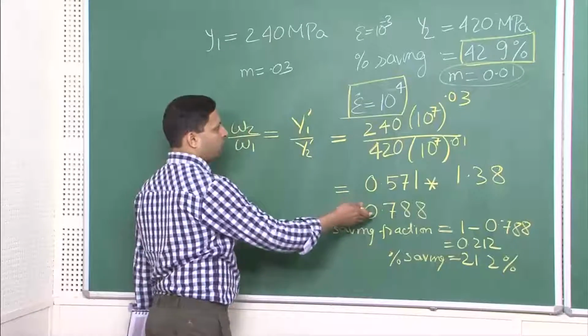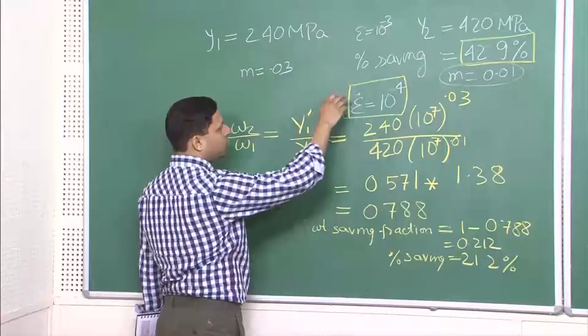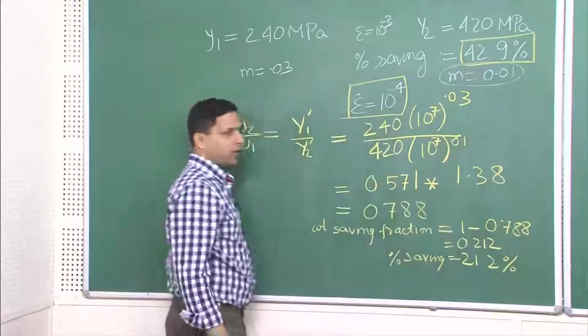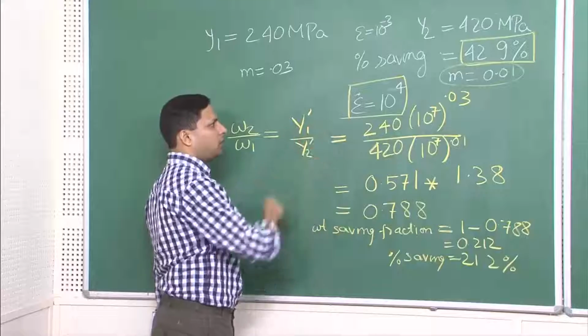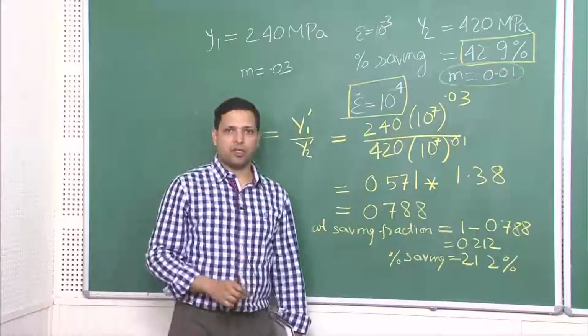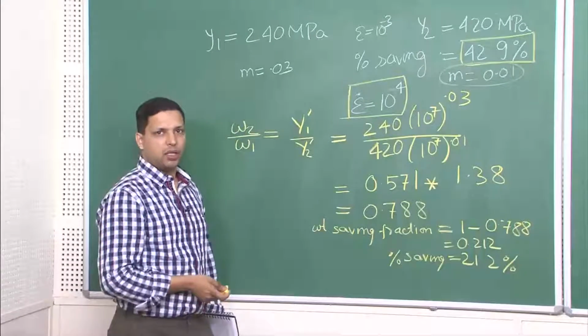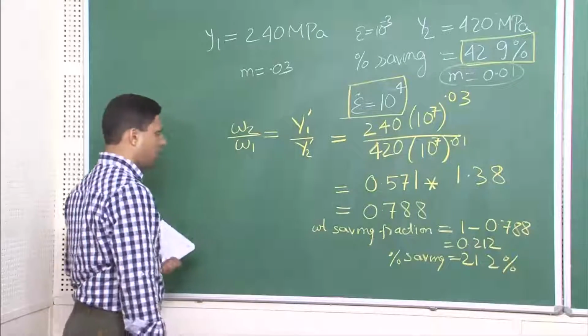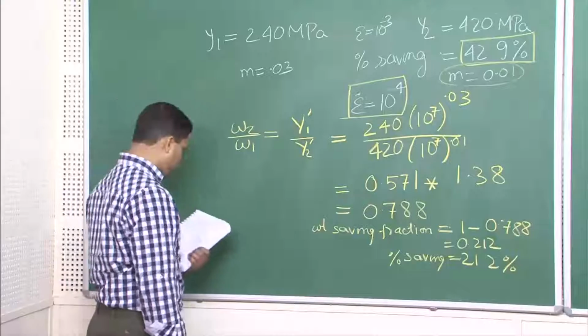While if we had calculated just assuming the previous one, it would have come out to close to 5.7. So, in that case we said we have to use only 57% of the thickness that we would use in high strength low alloy steel. So, that is the importance of understanding the effect of strain rate.